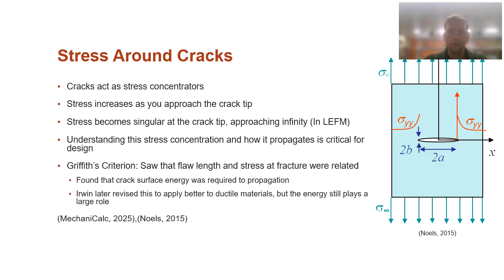We'll start off simple: stress around the cracks. We just saw a little bit of diagram about how stress is concentrating at the crack tip, and again, that's true for LEFM. In LEFM, that stress will become singular or infinite at the crack tip. Now, this creates some issues down the road when you're assuming infinity at a point, but we work past it, and you'll see this in a second from Griffith and Irwin.